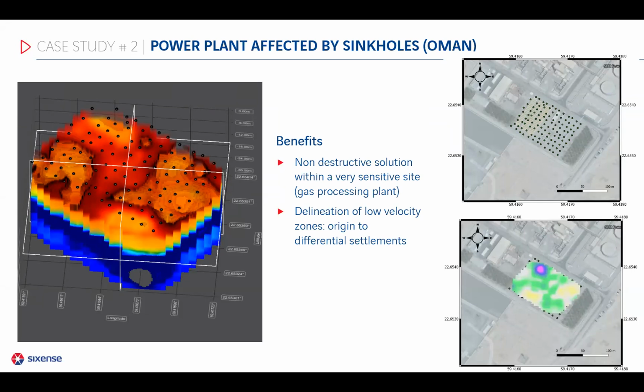we have compared these results to the observed settlement at surface and the sinkholes locations at surface to understand the correspondence between the two. And it appears that the settlements and the sinkholes are generally related with the most important thickness of soft materials in the first layer, and also where the seismic velocity in this first layer is the lowest. That means where the shear strength is also the weakest. So there was a good correlation between the two, observation from the surface plus the Vs velocity model.